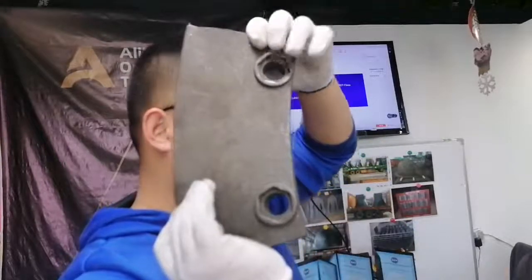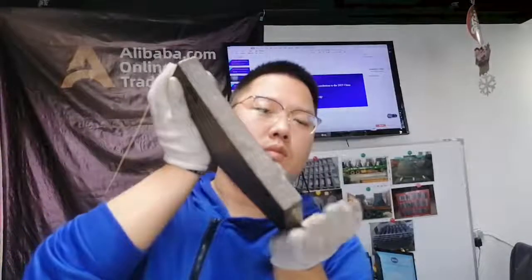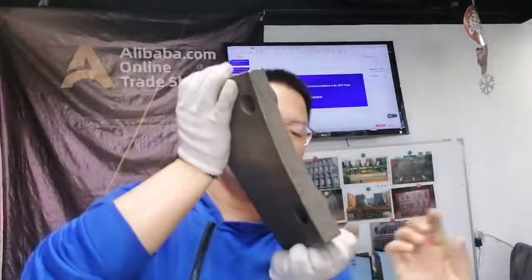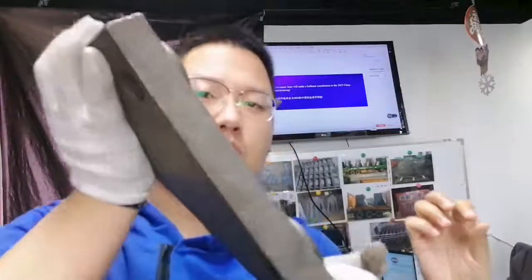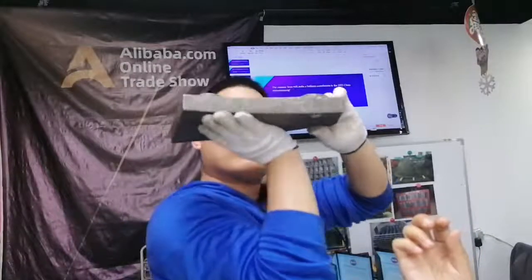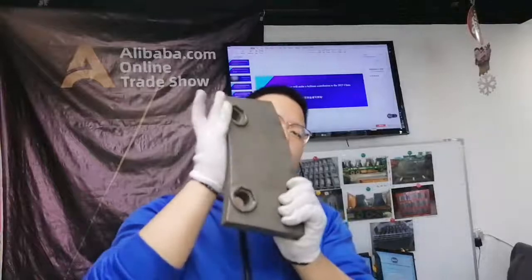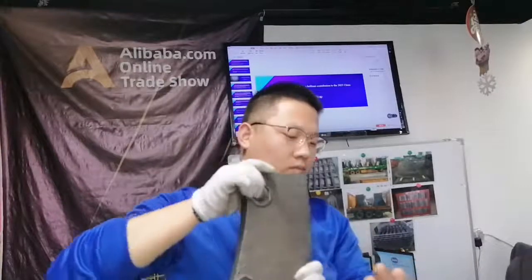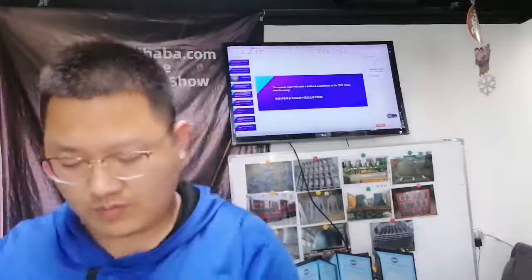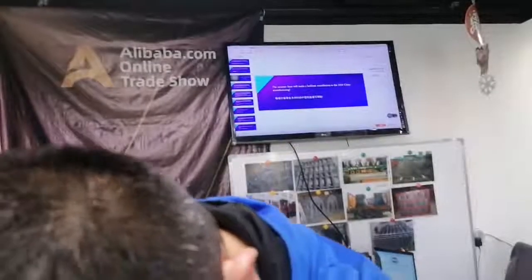So we have to consider very excellent wear performance ceramic. Because in such kind of working condition, the pellet size is just about 20 millimeter, so there is no big impact. It just pushes slowly. So we can adopt ceramic mill liners.